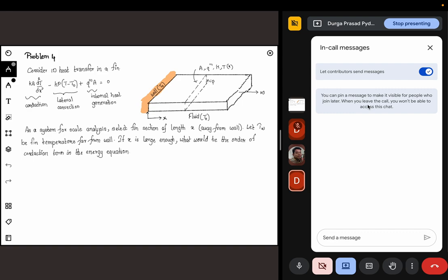And the governing equation is like this. So this is slightly different from the previous equation we have seen. For one, there is no velocity here, because we are writing the governing equation inside the solid medium, where the advection component velocities are very less. So there is no convection term. We still have the internal heat generation term, and then we have the surface term.